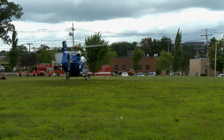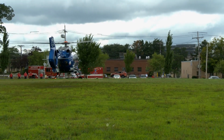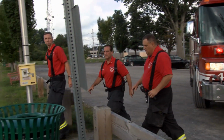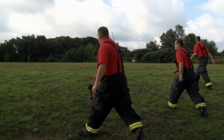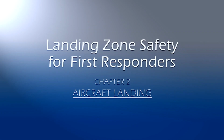Vehicles near the LZ should not be in motion when the helicopter is on final approach or landing or preparing for liftoff. This concludes our chapter on preparing the LZ. You should now have a clear understanding of how to successfully prepare an LZ under any condition. Our next chapter covers the helicopter landing phase.